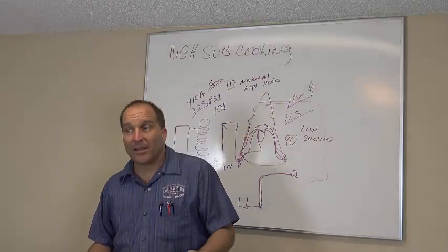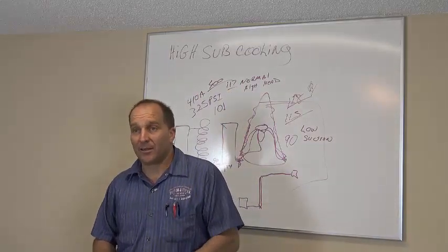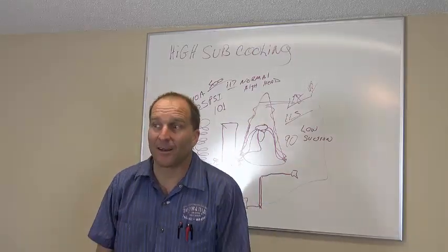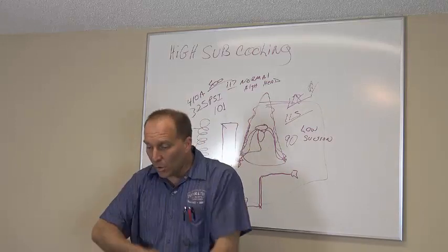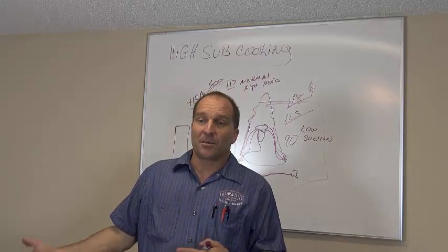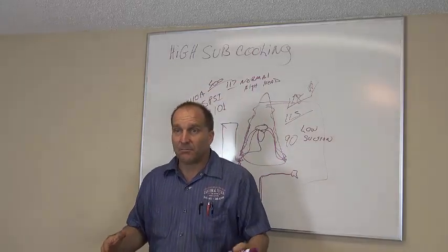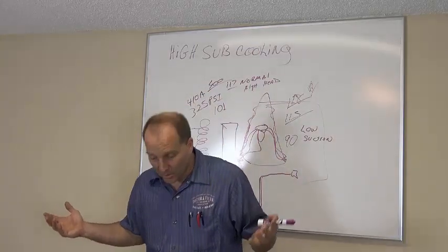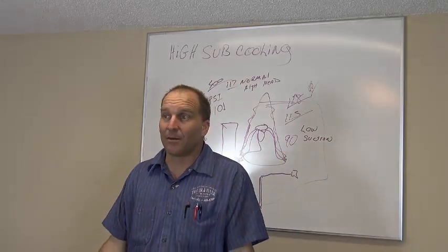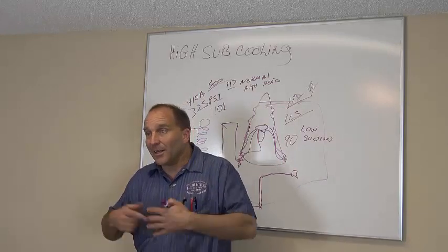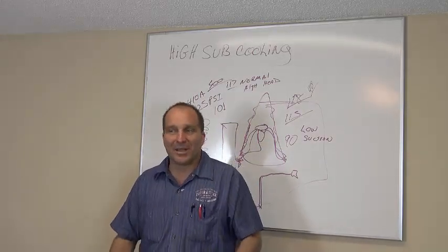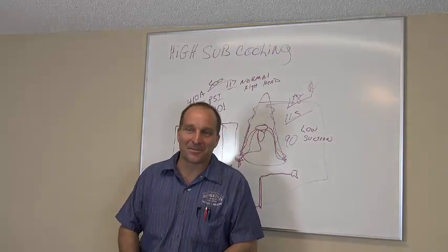So how is cleaning a condenser? What do you do when you clean a condenser? You literally take the fan motor off of it. You clean all the leaves out of the inside of it and take them out. Then you hose the inside of it out and get the leaves out of it. Because if the customer comes home and sees that you were supposed to clean the condenser, he goes and looks in the inside, it's full of leaves on the inside. Did you clean it? No. Well, you did clean the condenser coils, and the leaves literally affect nothing, but you didn't clean it. It's still dirty.